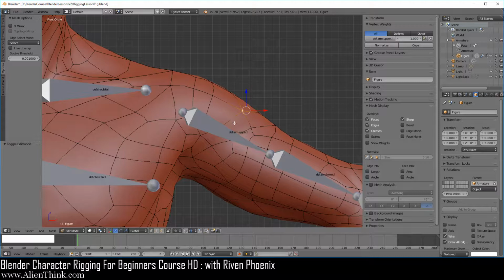So this tells you that when you are going through the rigging process, you want to be working with the low resolution version of the figure, and Blender will take care of assigning the additional vertex groups to these surrounding mathematically generated faces automatically. Okay, so now notice that we just assigned this vertex group to this vertex.